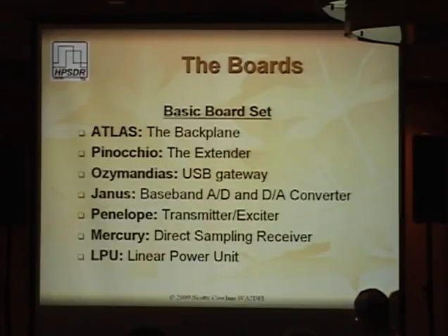Basically, you connect your antenna to the A to D. That's what it is. Now, it's not quite that simple, because you do have to have an anti-alias filter. We have a preamp in line also, and we have a selectable attenuator.